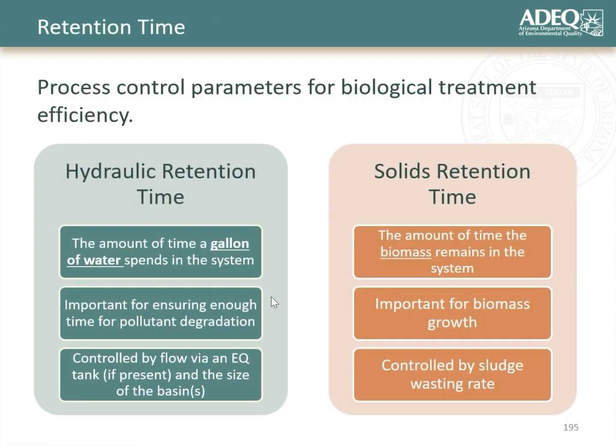So when you talk about hydraulic retention time and solids retention time, you think that because they both have retention time, they're the same thing. Well, there are some unique characteristics associated with this. Hydraulic residence time is simply the amount of time that a gallon of water spends in the system. So effectively, if you have a 100-gallon tank and a flow rate of 100 gallons per minute, the volume of 100 gallons is going to spend 1 minute in that tank and then flow out. It's just how much time it sits in there.